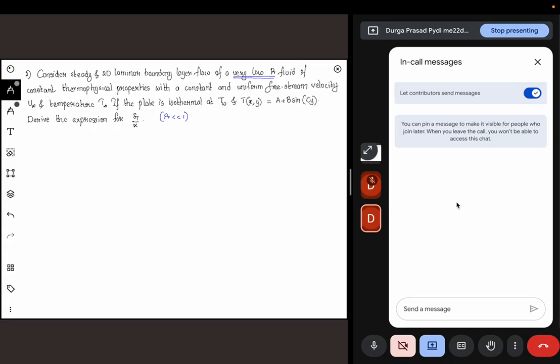The other one is the temperature profile. We have assumed a cubic profile. Now we are assuming some other profile here. But the difference is not in the type of profile we are assuming. The key difference that you have to identify is that previously, when we assumed a cubic profile, we had four unknown constants that needed to be determined. However, now we have only three constants. So which means one of the boundary conditions that we were using before cannot be used in this particular problem.